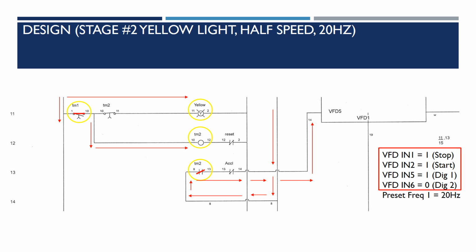This completes this stage. However, I do want to mention a few things while we're here that I forgot to mention earlier. All of our timed coils, you'll notice, have a normally closed reset contact on them. We'll talk about that as we get down into the reset portion, but that is how we continuously cycle this and reset these coils that are energized.